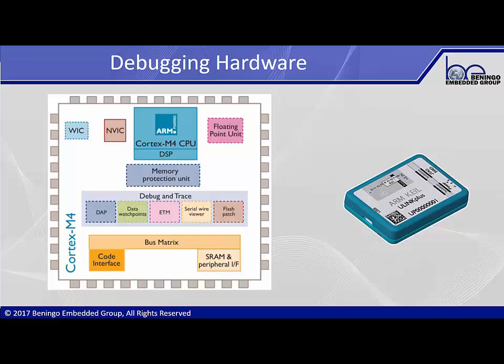We can install JLink software on it so that we can get tracing capabilities. But because the debugger comes with the development kit, it's not a high-end debugger. So what you'll find is that it runs relatively slow. You can still do event tracing, but it's not going to have the throughput that you would get if you purchased a $300 or $400 debugging tool. So we want to make sure that we have a good debugging capability with us, like a debugger.